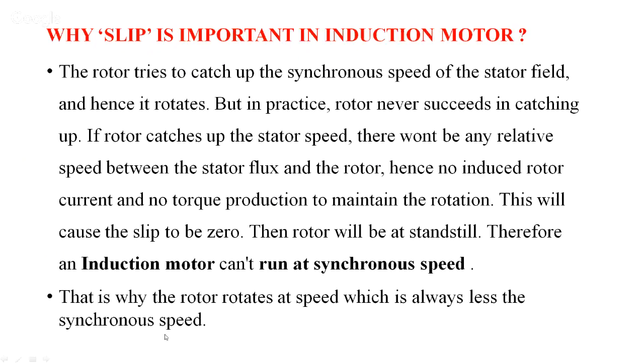If it catches up, then there is no relative difference in speed between the two fluxes, that is the rotor flux and the stator flux. Then there will be no induced EMF, no induced current, and no torque production. Therefore, the motor will stop working. Therefore, the rotor always rotates at a speed which is less than the synchronous speed.